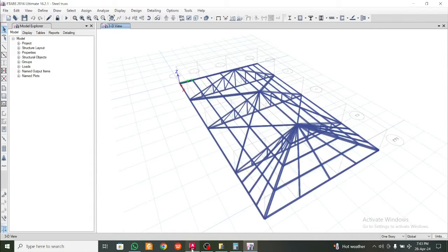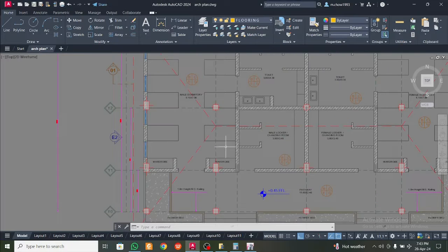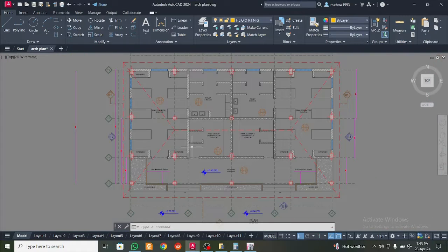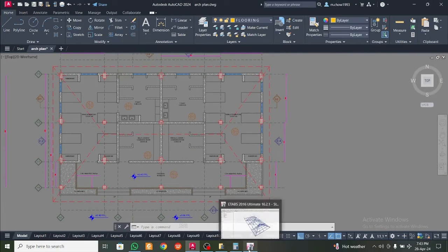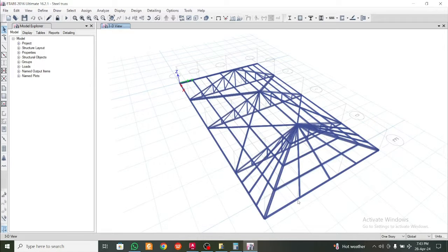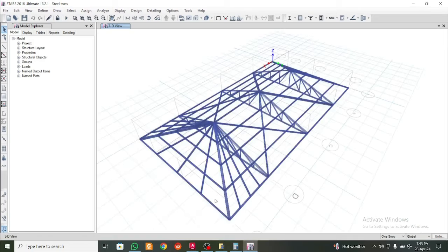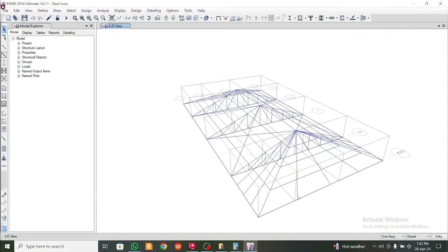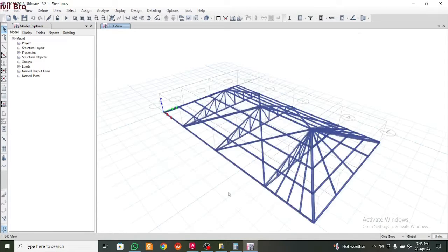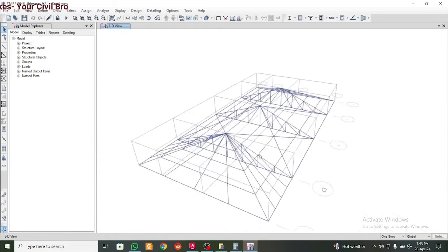In this case, we're using a PPGL sheet. You can have PPGL sheets of Tata or SRMB, or many good companies, but you can use simple tin sheets or PPGL sheets. There are two types of sheets mainly, PPGL and PPGI. There's some difference, you can check this out. PPGL is the more advanced version, lighter and better. So this simple roof system design we will do.